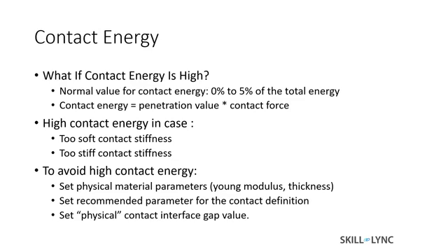Contact energy can mainly be taken as penetration value into contact force. Then you need to make sure that the contact stiffness is set right, so you can follow the recommended practices, and then you can go about getting control of your contact energies.